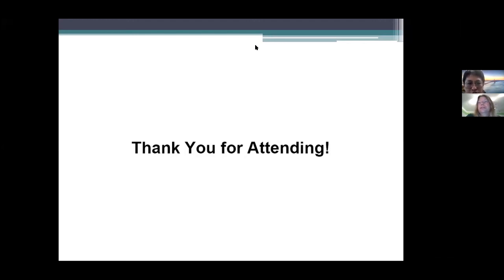Which is the switch that you use for the DC to DC converter? Which is the switch? Just the MPPT direct with the DC to DC converter, Mr. El Mustafa. I have not used a particular switch, but if we go back to my presentation, we used a PWM, pulse width modulation converter, to switch the DC to DC converter. And we could use a MOSFET as a switch for the DC to DC converter.